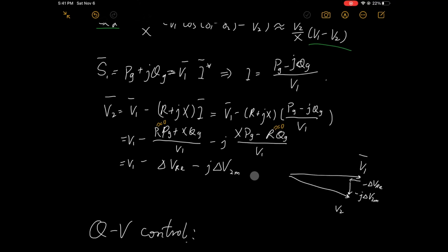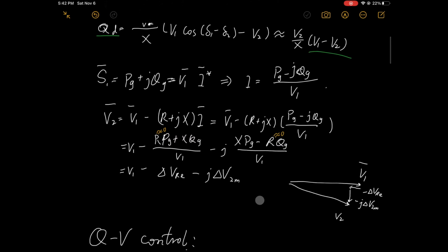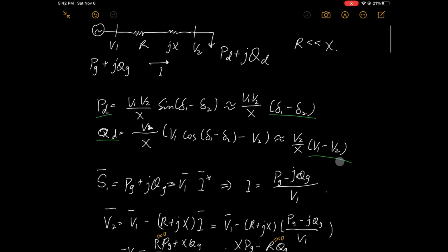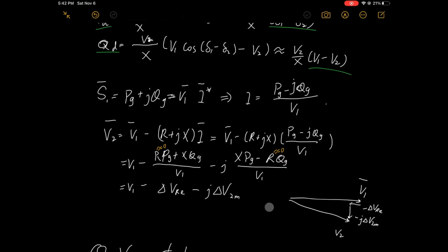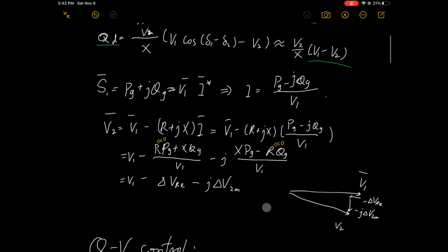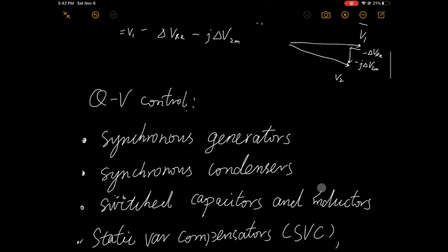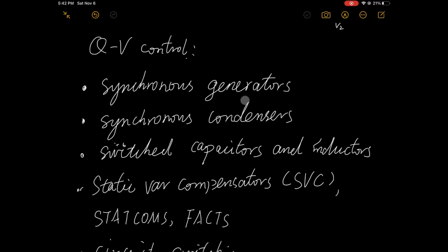In power systems, there are motors and transformers which are inductive because of magnetization. And there are series elements from transformers, cables, and lines which bring reactive losses. All of these components require reactive power supply. Meanwhile, shunt elements such as line and cable capacitance can provide reactive gains. If we hope more reactive power supply, choices are as follows. Let's talk about them one by one.